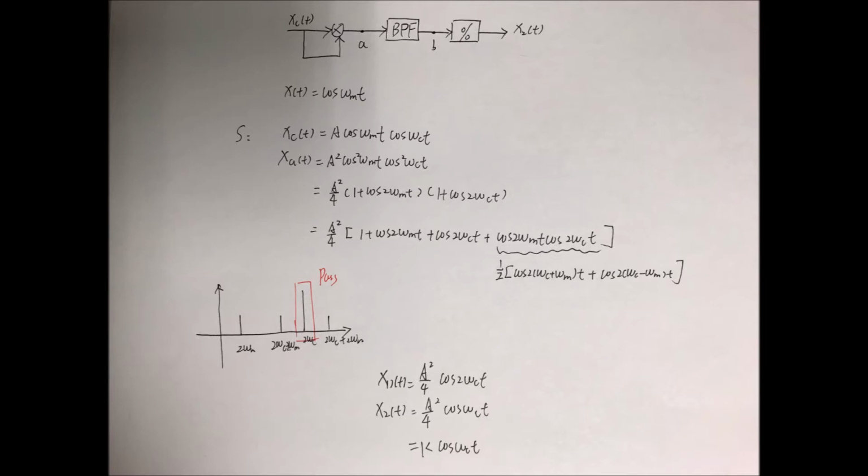We call this method reference extraction. We extract the reference from the received signal, and it's way more accurate compared with having a local oscillator. We know a high resolution oscillator is really expensive.